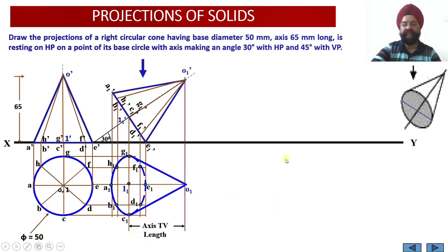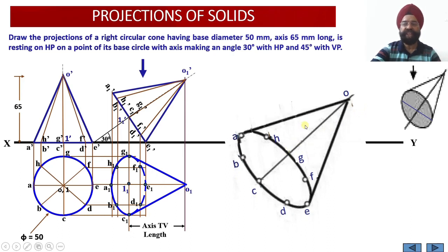And then again I am going to show you through this. Since the observer is going to look at this solid from the top, please check, this portion will be visible to the observer, whereas this portion has been covered by the projection of this portion of the cone. The upper semicircular portion is visible, the lower semicircular portion which corresponds to EFD is not visible to the observer. So that is why the interiormost portion of this will be dotted.